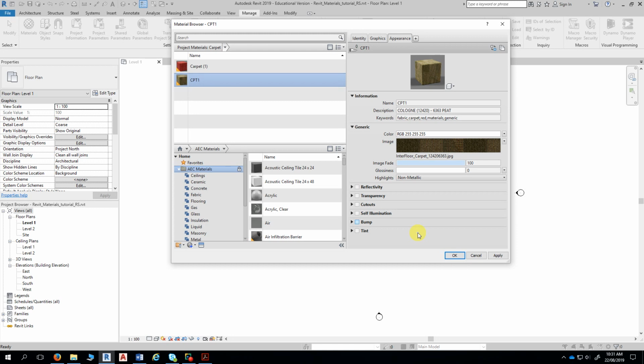A lot of these things with materials are experimentation. So if you do a rendering and think, let's see what the carpet looks like with bump ticked, and you render it and it looks pretty good, or if it's unticked and it looks flat, then you make the call. But the exercise is calling for that to be unticked.